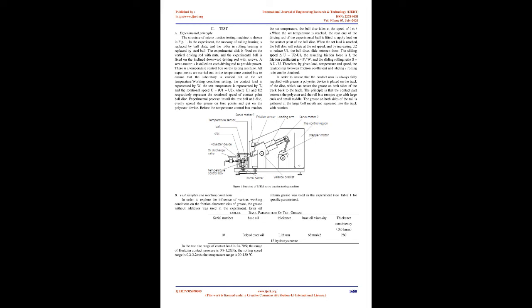[12] The results show that the higher the viscosity of base oil, the higher the content of thickener, the faster the rolling speed and the lower the temperature, the more obvious the degree of lack of grease is. The specific explanation is given in references [13-14]. The infrared spectrum analysis shows that thickener can promote the formation of oil film. [10] The experiment only verified the relationship between oil film thickness, friction coefficient, and thickener type under the condition of